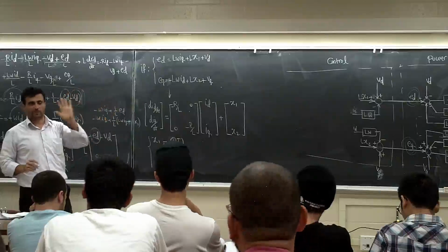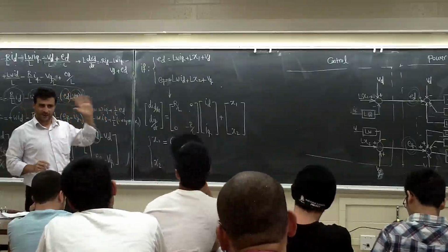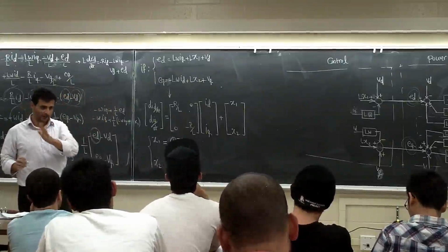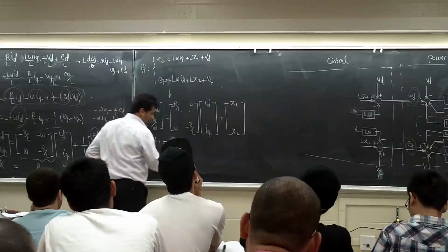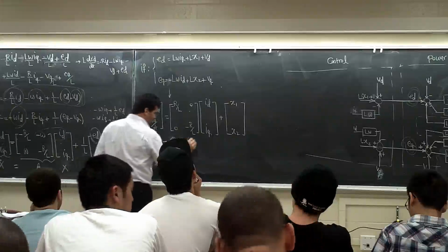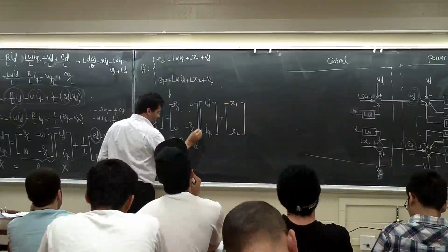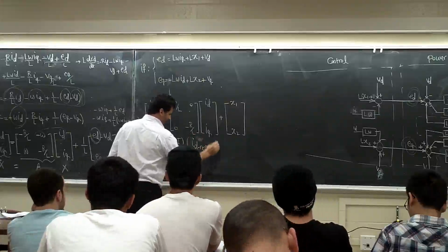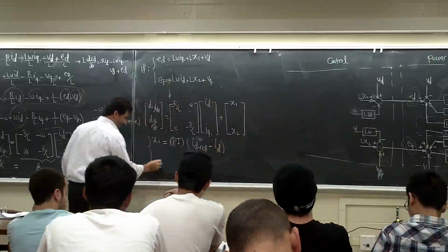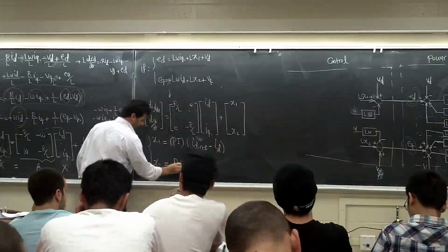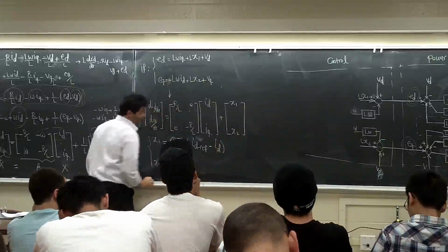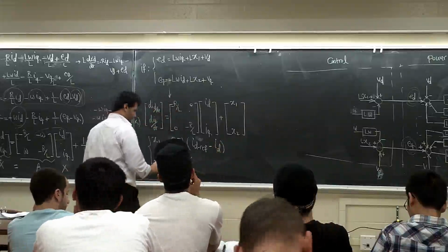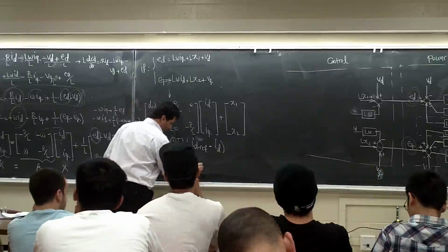We talked of KP plus KI over S, and then there's KP times parenthesis 1 plus 1 over tau S. Either way, you can just put the PI times ID star or ref, let's call it ref, minus ID, and this one is PI times IQ ref.